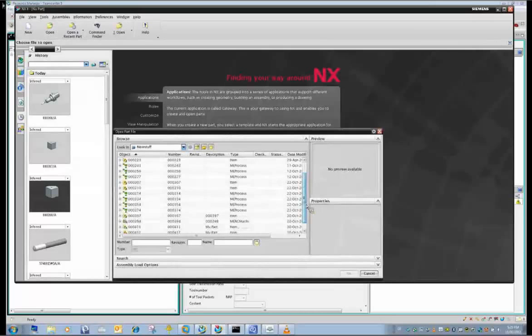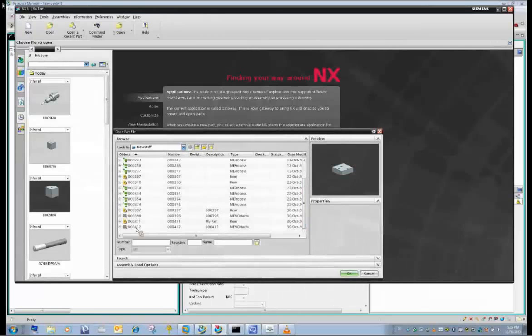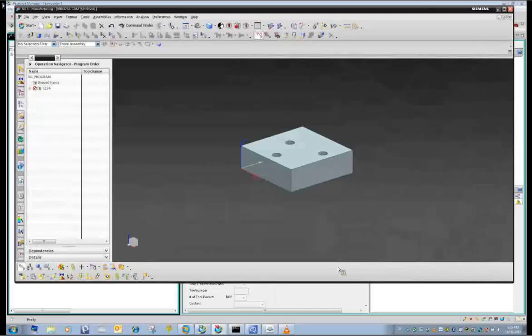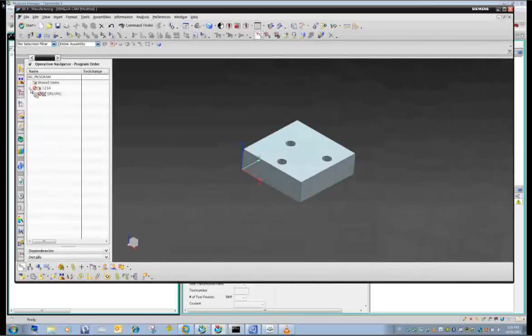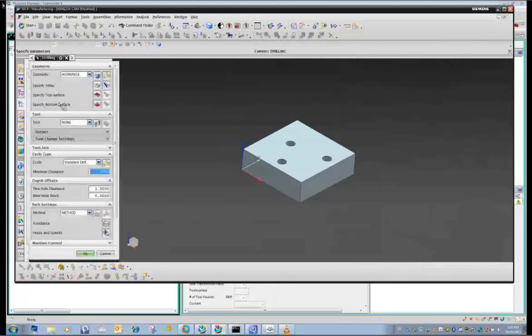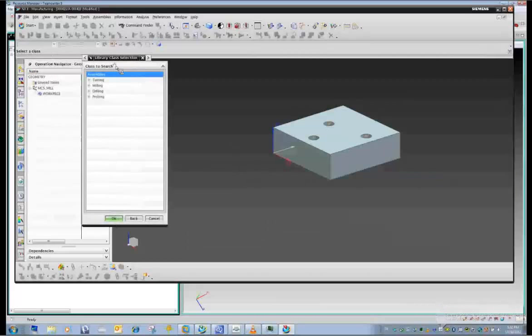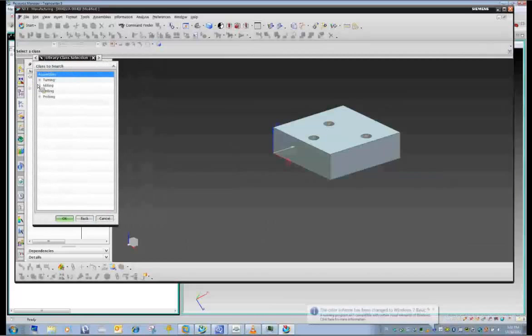little setup. So that in the next step, I just want to show you how you can use the tool we just created and stored in the database in the CAM application. So here we are. We're in the library selection. In the library selection, I can go for the drilling tool. So we have basically exactly the same view, but now only on the tool assemblies.